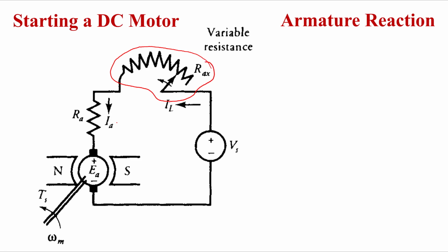And we can see it is gradually shifting the contacts and it will finally cut the whole resistance away from the circuit till the motor achieves the rated speed or the normal speed, right? So initially it will start with the full resistance, then it will gradually cut.